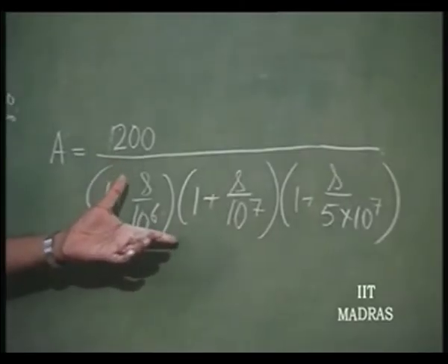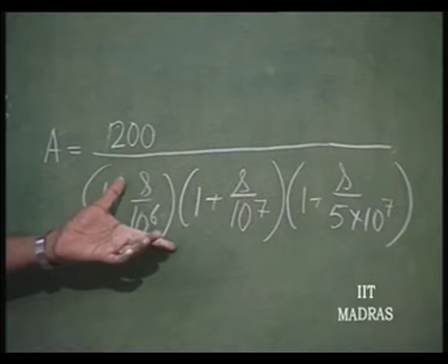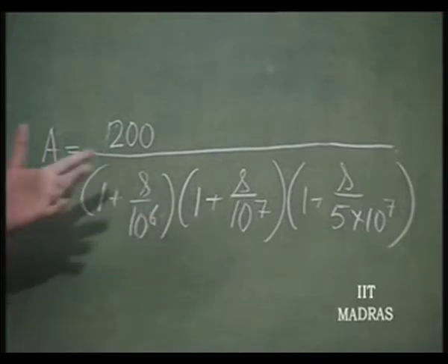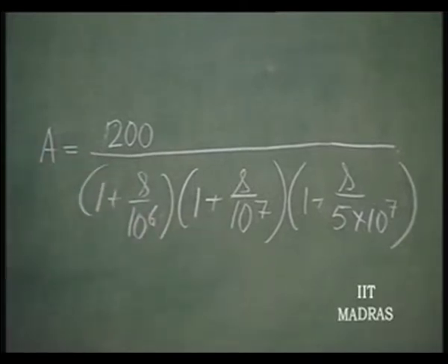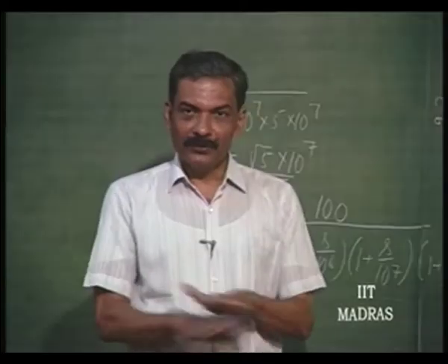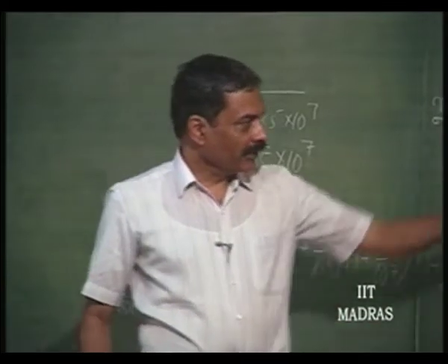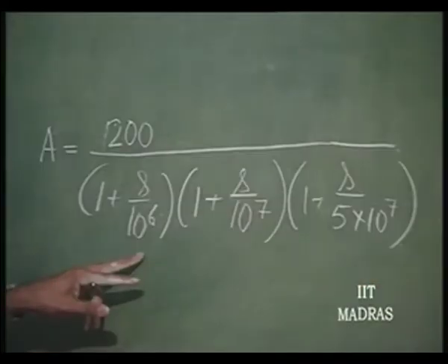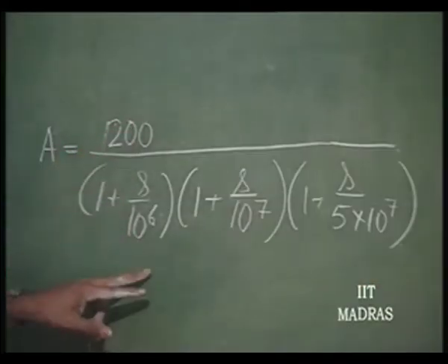There are 3 or more poles associated with it. If it is less than 3, if it is 2 or 1, there is absolutely no frequency compensation and the gain bandwidth product is straight away the gain into the first pole frequency.